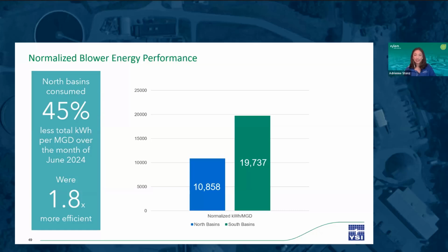Additionally, sensor maintenance and placement within the process are very important. Cleaning, properly checking, and validating your sensors can lead to reliable, efficient wastewater treatment systems. You heard from John on his tips and schedule for verifying these sensors, and from the graphs we looked at of sensor data, you can see how his practices go a long way in maintaining these probes' ability to read accurately across their measuring range.